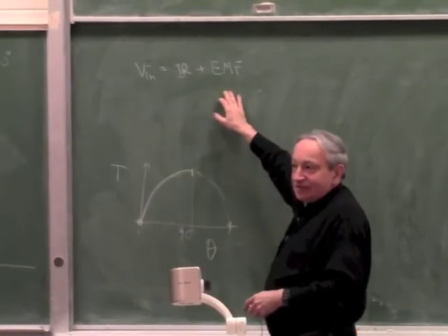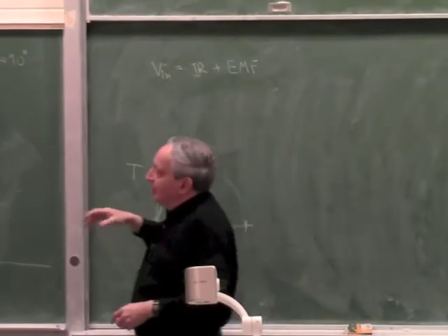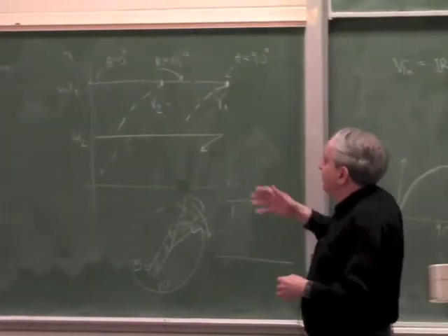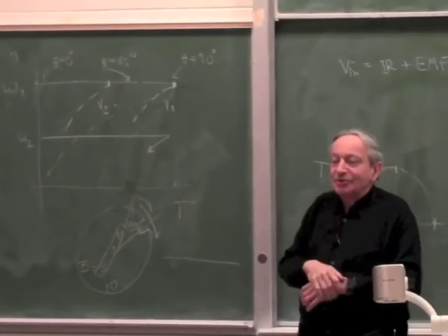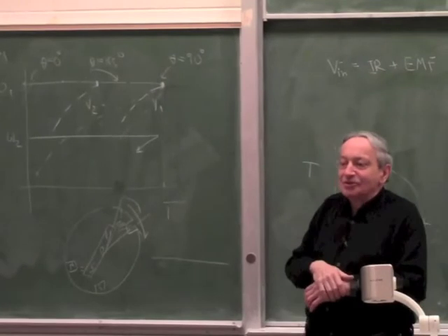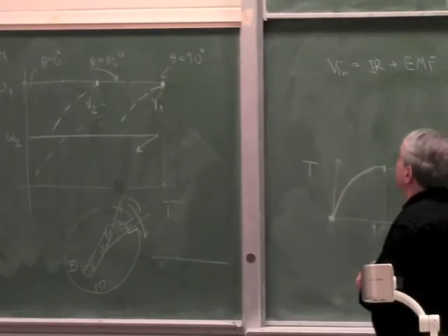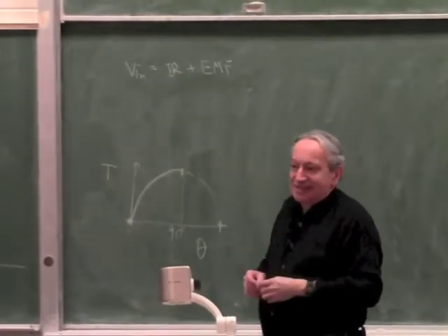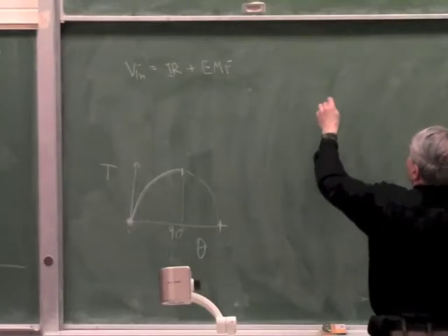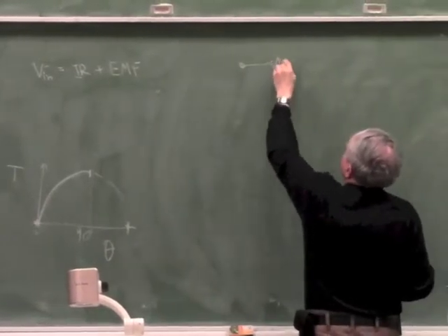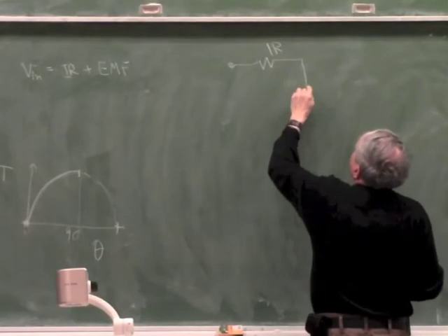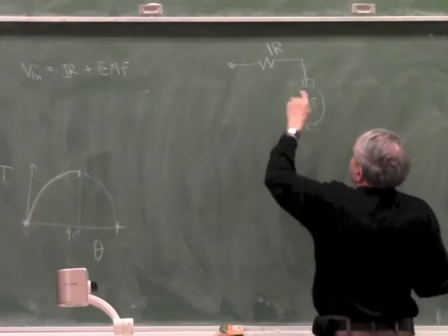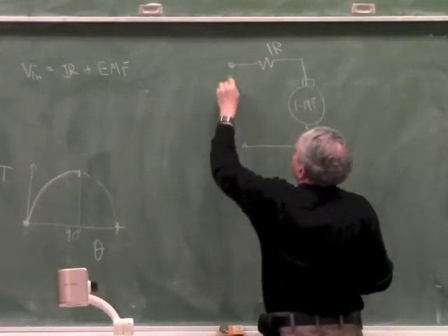So we talked a lot about the back EMF in DC motors, but there is also a back EMF in AC motors. In AC motors it's a bit more complicated because there is also an inductive component. So actually the R in an AC motor is not only R, but it's actually Z. Because the way they draw the model, in a DC motor we drew IR, and then we drew the back EMF created by the rotating rotor, and this had to be equal to V.